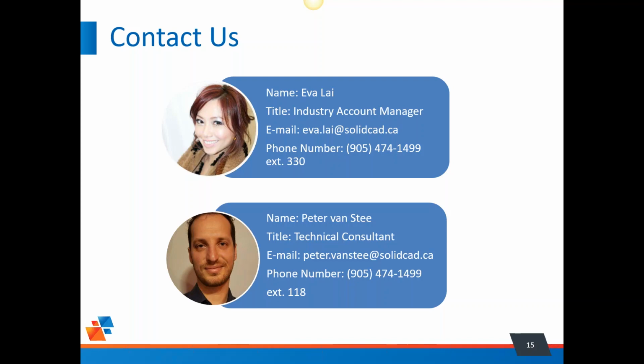It's not live to whenever every user synchronizes. It's a publish up to BIM 360, and that is the latest and greatest snapshot of that file. We can set automatic publishing so that, let's say, at the end of every day or every week, it publishes to BIM 360 and you get a snapshot of the Revit model at that point.